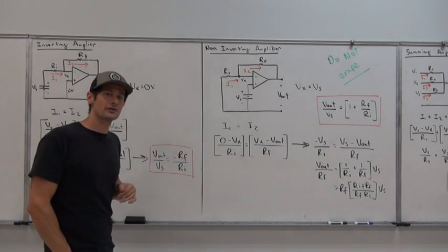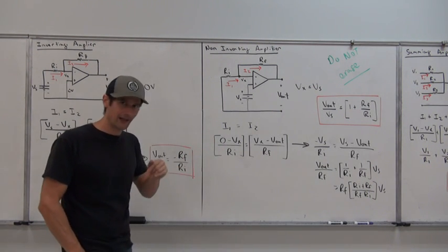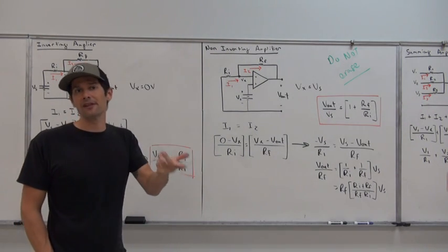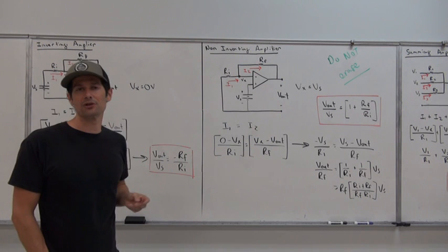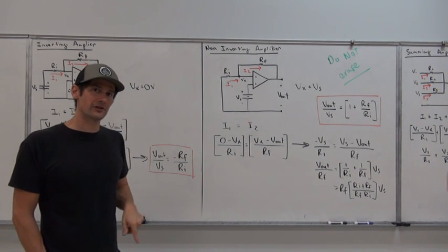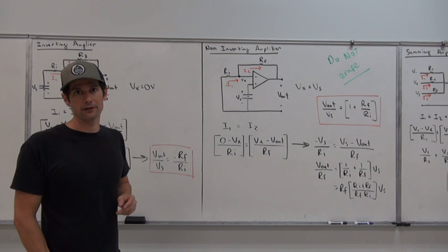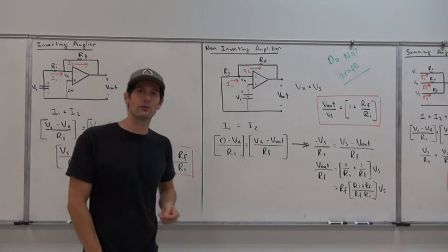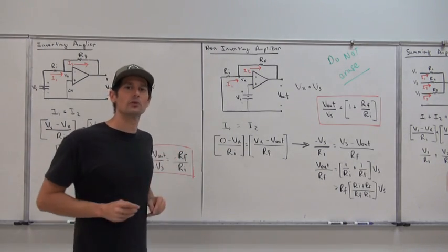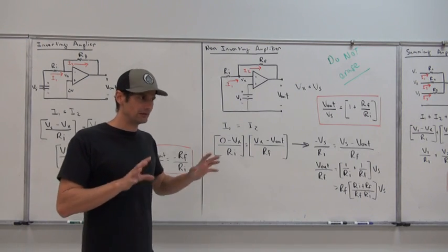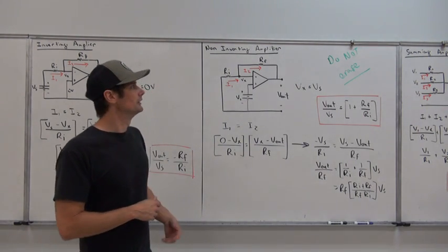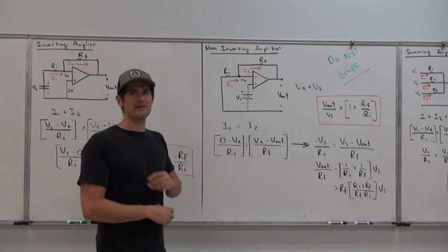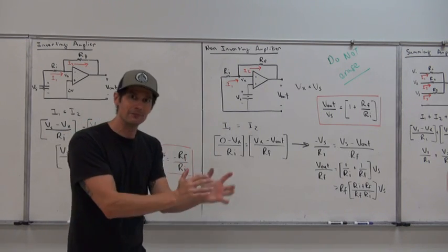And utilizing those conditions that we had, that V1 and V2 had to be the same, and also the fact that the internal resistance was so high, approaching infinity, we saw examples where that internal resistance was 2 million, so we can't have any current through there. Due to those notions, we can apply nodal methods, KCL, very quickly and determine the relationship between the output voltage and the input voltage very efficiently. We're going to go at almost lightning speed through each of these, but it explains exactly how these relationships of the output voltage to the input are derived.